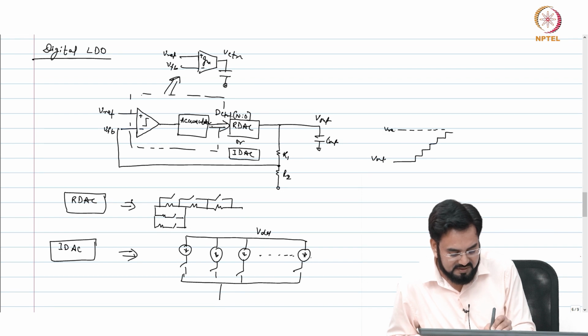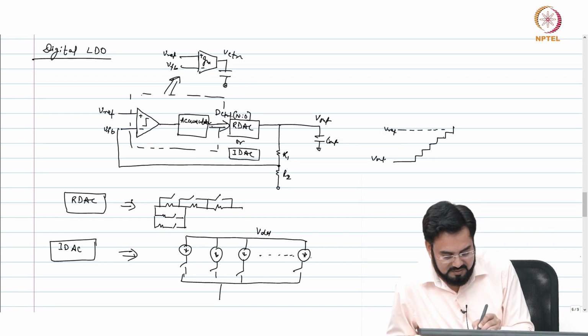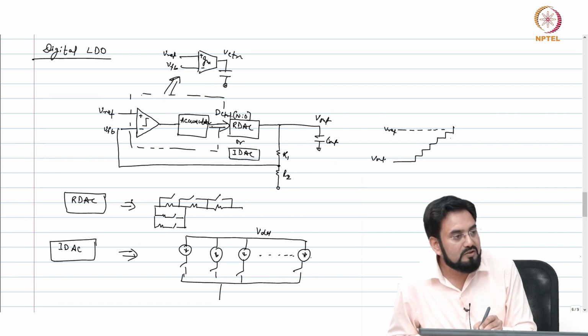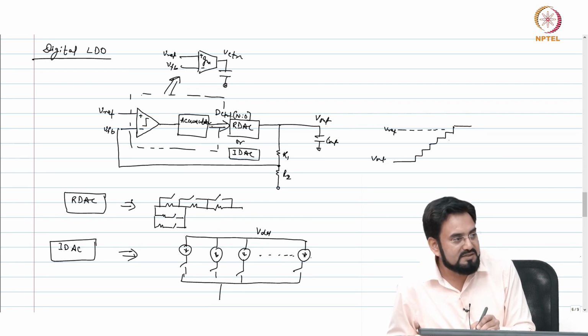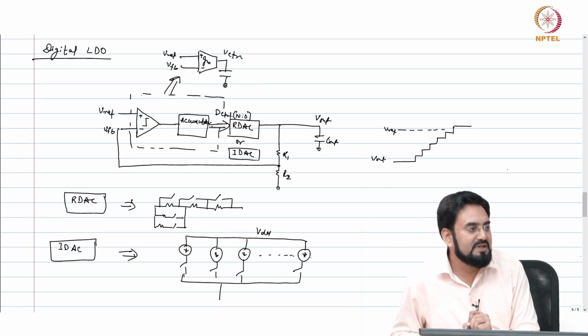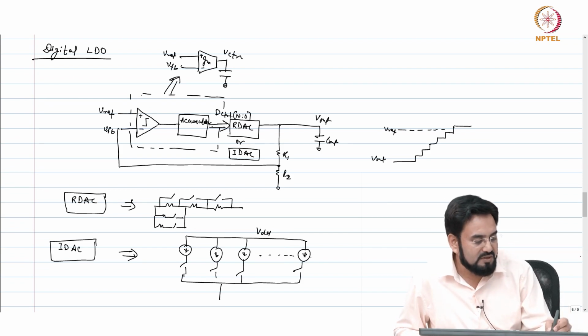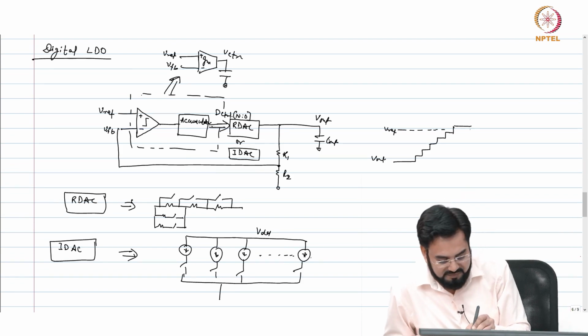So now this was still low, but if you put the next code, then it crosses. So the comparator output will be high here, and here your comparator output will be low. Then in the feedback, this is low, so again it will turn high. So it will keep doing this actually, high low, high low.